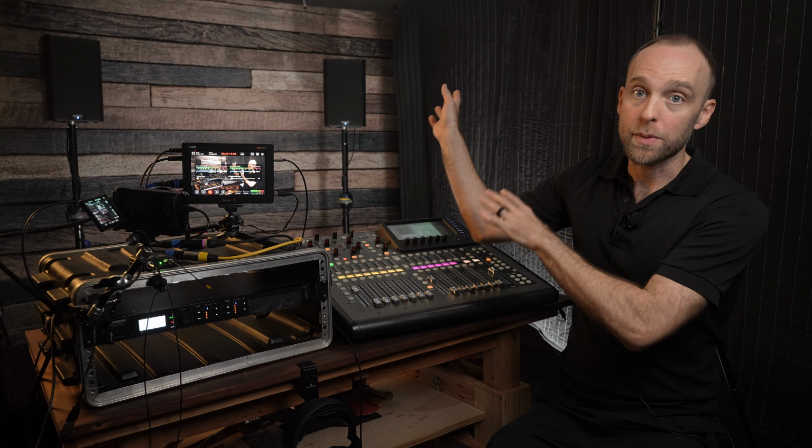But that's not what preamps are for. Mic preamps are not there for volume control out of your speakers. Mic preamps are there to gain our low-level mic signals, which generate a very small amount of electrical voltage, up to a stronger line-level voltage for the console, because the console was designed to work most efficiently, that is, with as little noise as possible, when the audio traveling through its circuits is at line level.